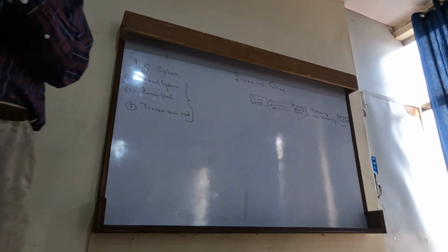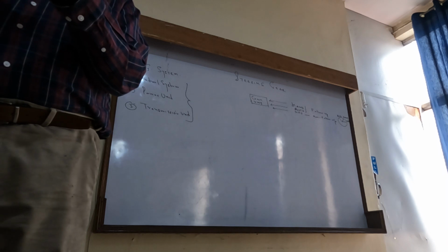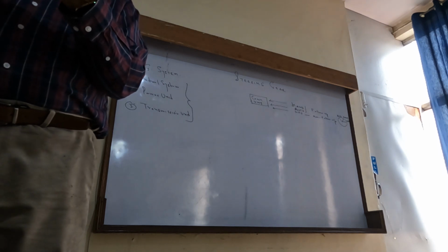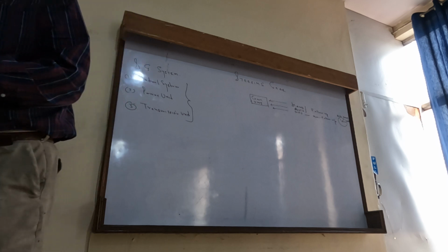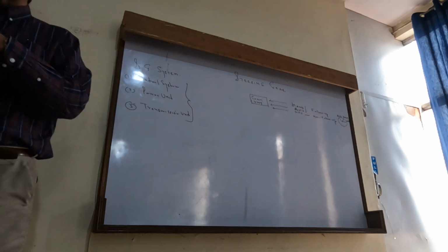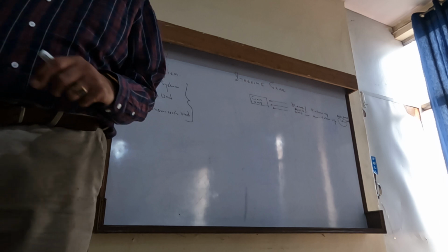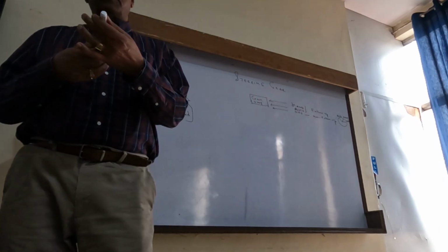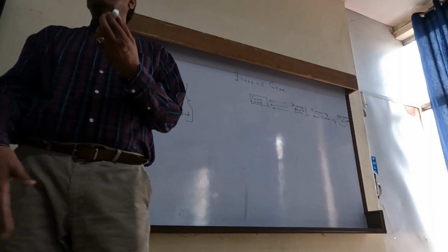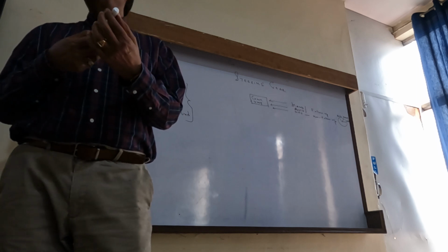It does not matter whether I am moving it this much or this much, because it is not a proportional action. Whereas in hand steering, if you move it to 10 degrees port, the rudder will go to 10 degrees port and stop. That is a follow-up system, because it is following your instructions. But the non-follow-up system does not know; there is no feedback there.